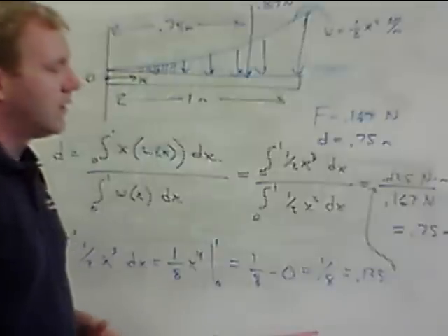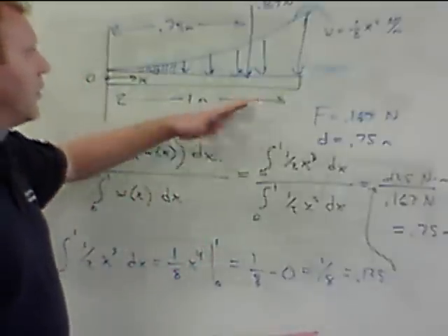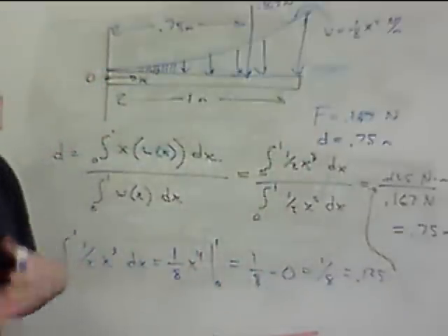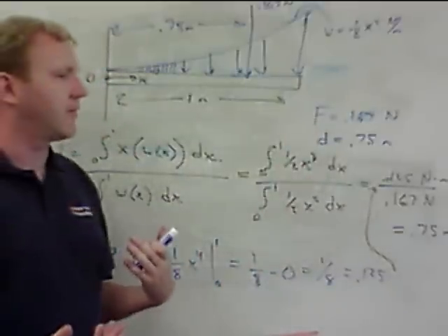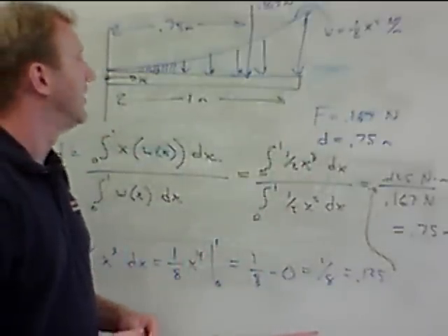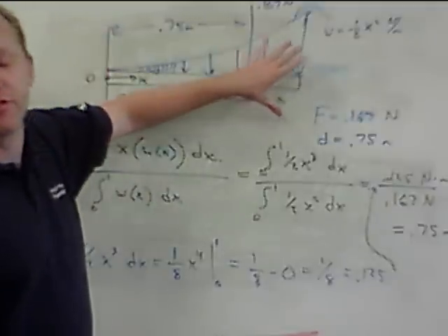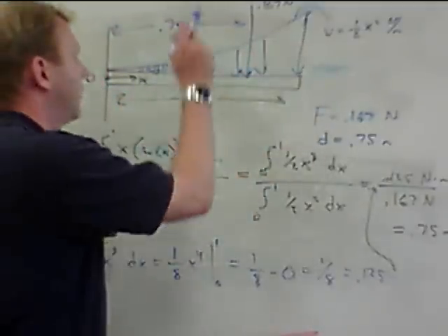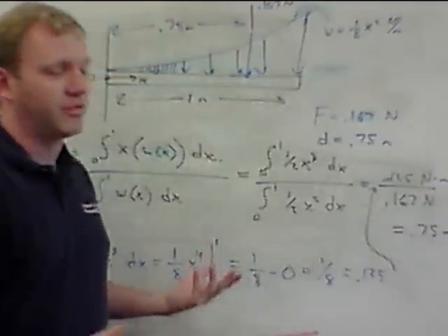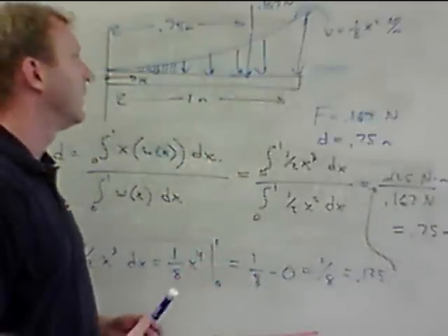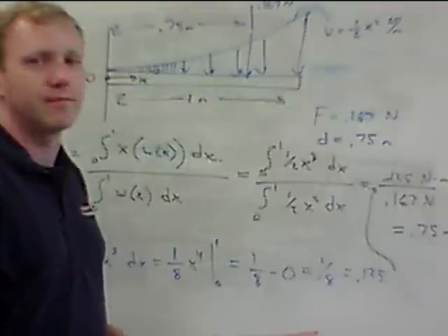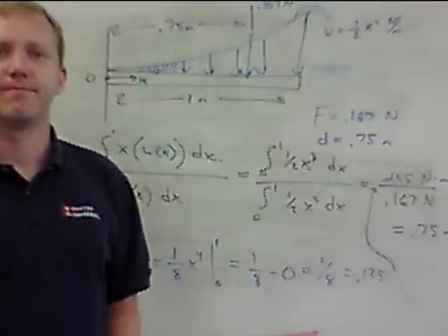We will eventually get to the point where we combine distributed loads with point forces, but really that's not any different or difficult than anything else we've done. You simply start by reducing your distributed load to a point force, redraw your diagram with your new point force plus any other point forces you have in your problem, and you go ahead and solve from there, which we'll see in some of the examples in class. And that wraps this one.